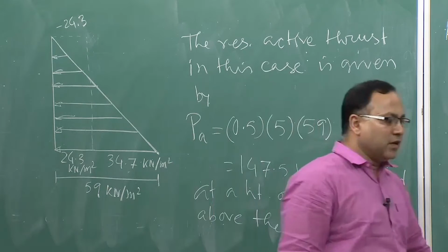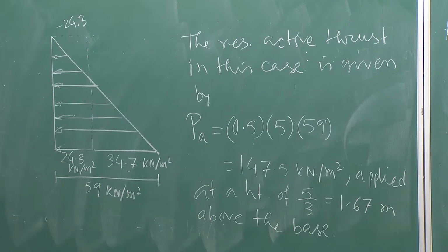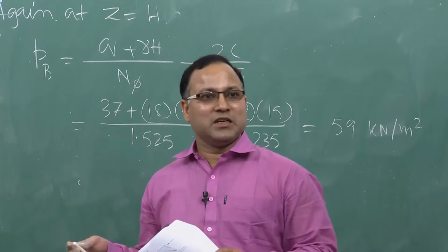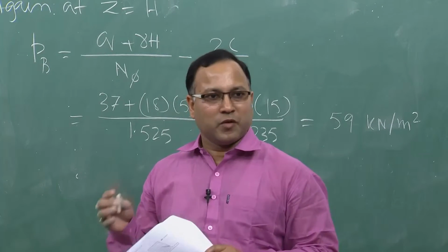Okay. I hope you have understood this problem. This was a very interesting problem. How to get rid of tension cracks, right? By putting this surcharge, you can get rid of tension, because you are neutralizing the tension whatever is getting developed at the top of the wall.